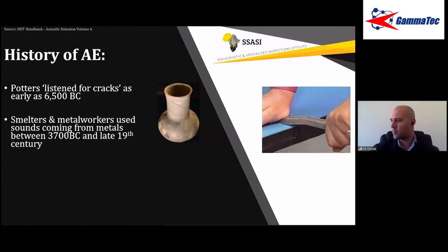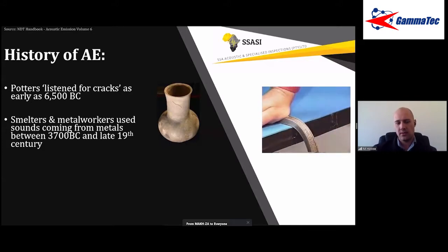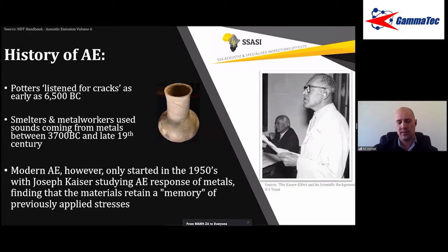Here we have an example of what stress relief in acoustic sound generated sounds like. And you have multiple metals that do this. So tin is a noteworthy one here, iron, cadmium, and zinc. So the early metal workers used this quite extensively. And that's sort of the roots of acoustic emission.